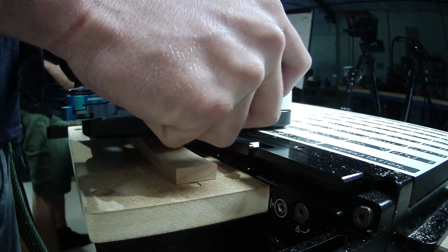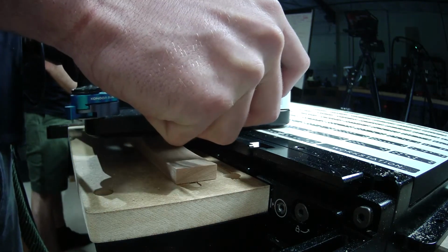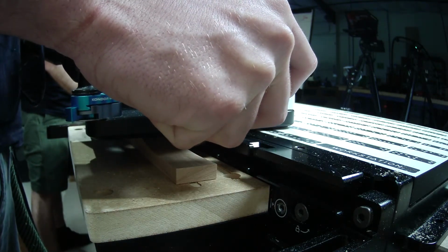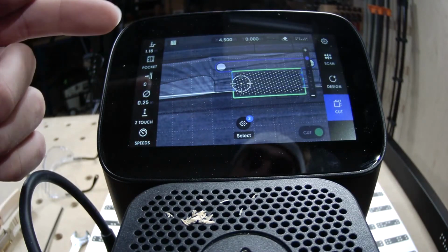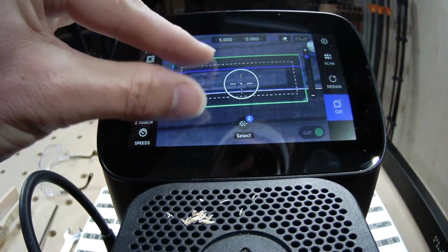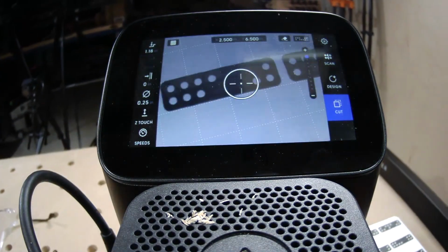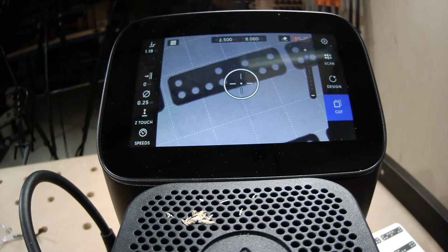So we come over here and we place it, and now that pocket is actually going to be overlaid on the edge of the material, because you can see the white grid showing me that edge of the material. And here the pocket now is actually extended over. We would cut the pocket, come back, change the inside, and now we're over cutting the edge of that material. So that would be step 2, and you'll be able to experience this on the Shaper Hub yourself.